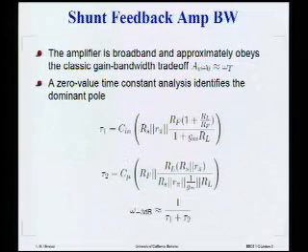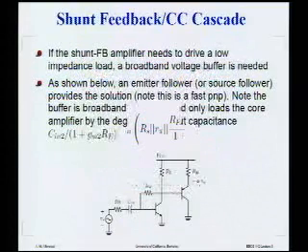And again, if you make some approximations, you can show that this is roughly true, within a factor actually, that the voltage gain of this device times the 3 dB bandwidth is roughly the omega T of the device. Again, within some multiplicative factor. Okay? So again, if you're designing an amplifier and you're trying to optimize its performance, you would try to maximize, first of all, the device performance. You try to maximize the fT, and then you'd pick your impedances to get the gain and bandwidth that you can out of this amplifier. Okay? So I'm going very briefly through this because this is the topic of your homework. Don't want to bore you guys with it.